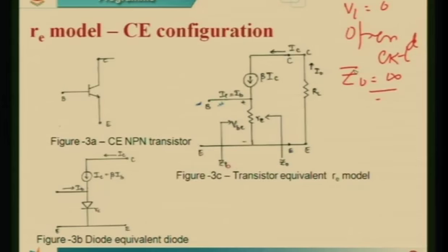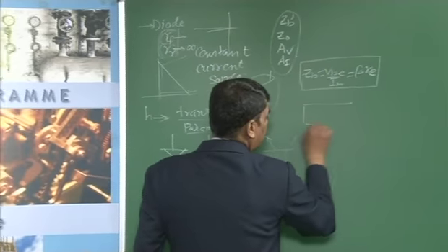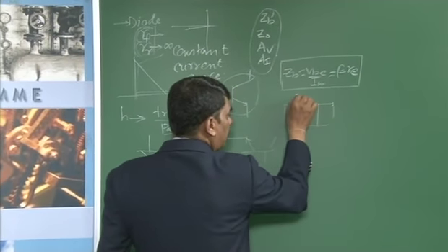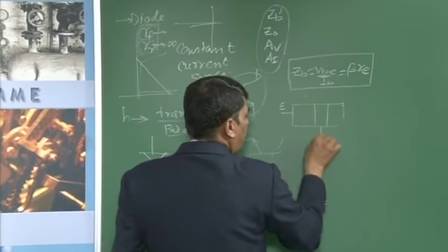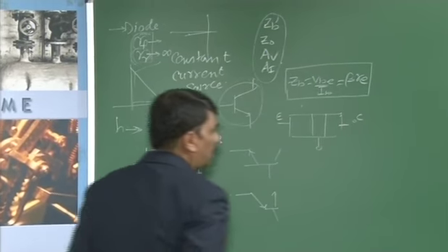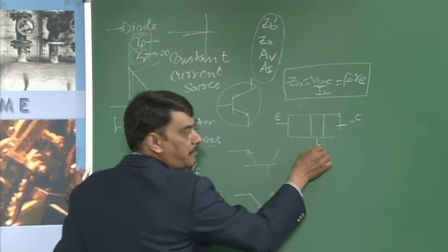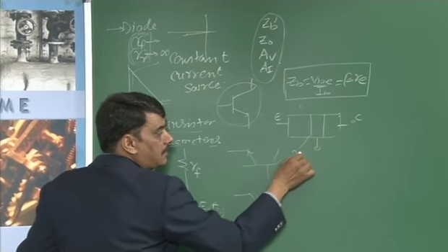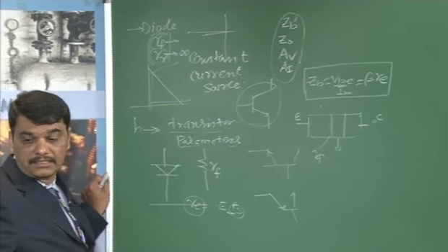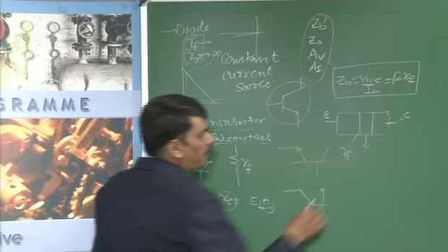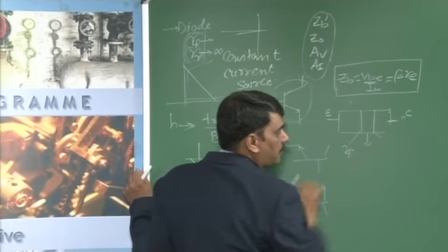But because we already defined a transistor as a transfer resistor, this is the transistor, with emitter, base and collector. Already we know that this junction is forward biased, and this resistance is denoted with RF. This junction is reverse biased, acting as an open circuit.